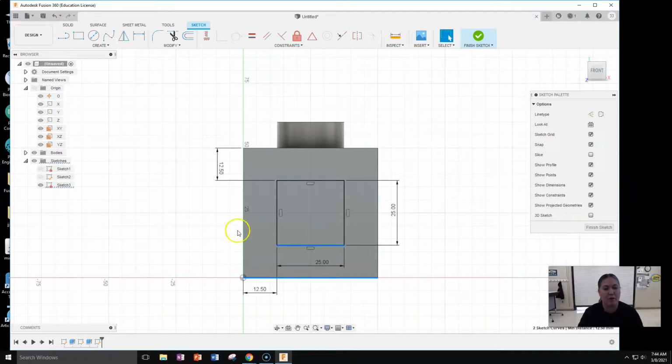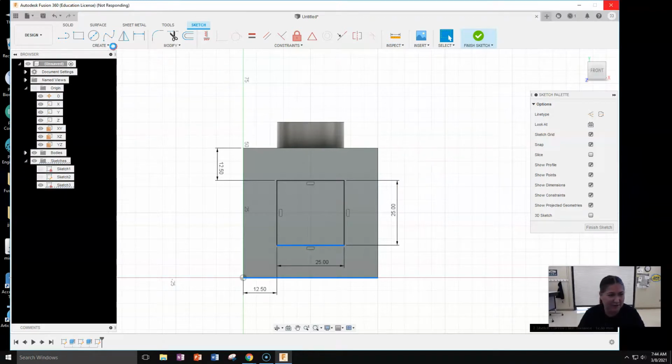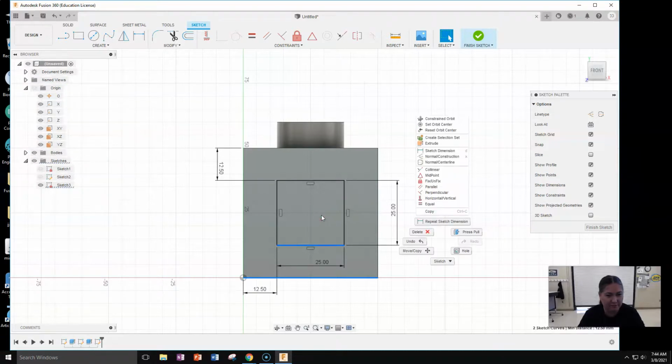Yeah. Okay, so you only need 2 dimensions, one in this space here, one in this space here, or you could have done it on the other side. It's entirely up to you, but you want to place that in the center there. And normally I can turn this a little bit to look at it, but I am definitely frozen right now. Okay, then we're just going to extrude that and we'll leave it there.